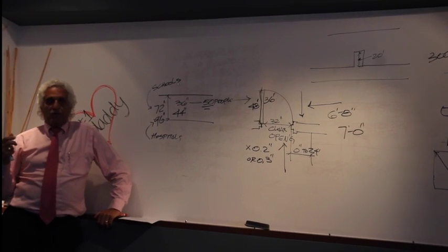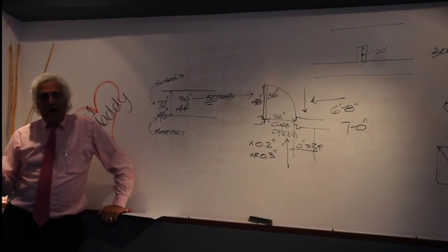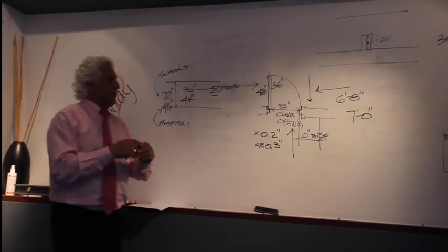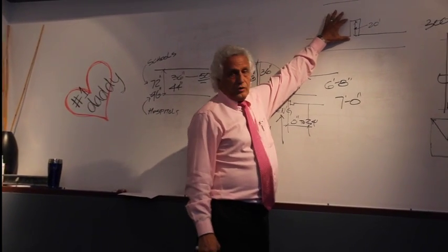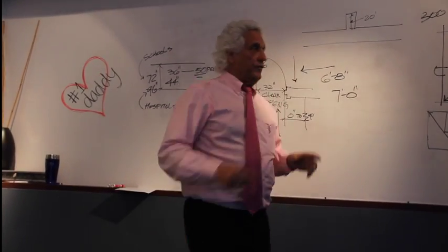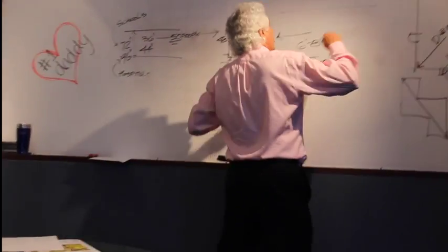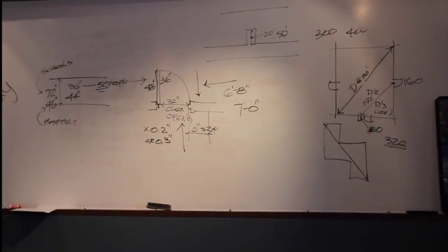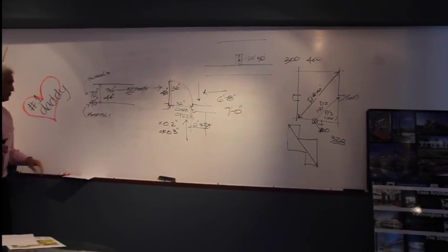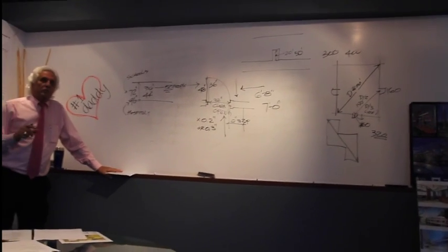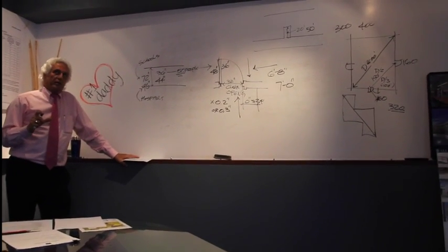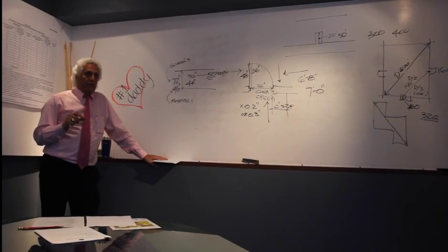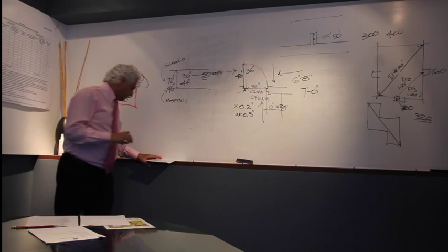They determined they could lose 7.5 seconds and not affect their life safety. So they determined they were backwards in that and said, okay, you can't have a dead-end corridor more than 20 feet. If you sprinkle the building, that dead-end corridor can be increased to 50 feet. Otherwise, the occupants would go down this. Remember, you're dealing with people that are going to be in a panic, and in a panic, you don't think in rational terms. You're going to have to be moving quickly, and your reasoning is not always there.